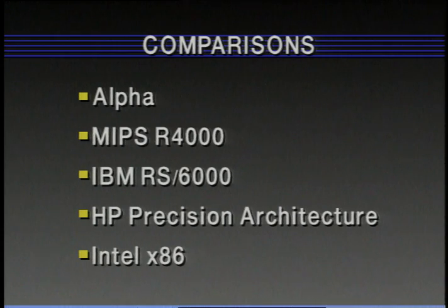One of the common questions I'm asked is, will CISC catch up? My comment on that is that the instruction set architecture there has a small number of registers and really shows a lot of the heritage from its 8-bit design. So I think what's happening is that the implementations are borrowing from a lot of the techniques that RISC computers use, but it's going to be impossible for that family to borrow from the architecture of the RISC instruction sets. Because of that, I think it's very unlikely that that architecture in the long run will ever catch up to where the RISC architectures are.